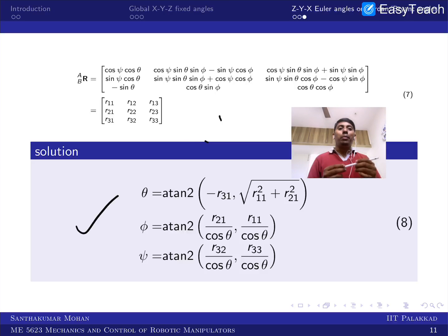In the geometrical model, this is associated with Cartesian coordinates: x, y, z, alpha, beta, gamma are the 6 parameters involved. We call these task space variables or operational space variables, whereas theta 1 to theta n are the configuration space variables.